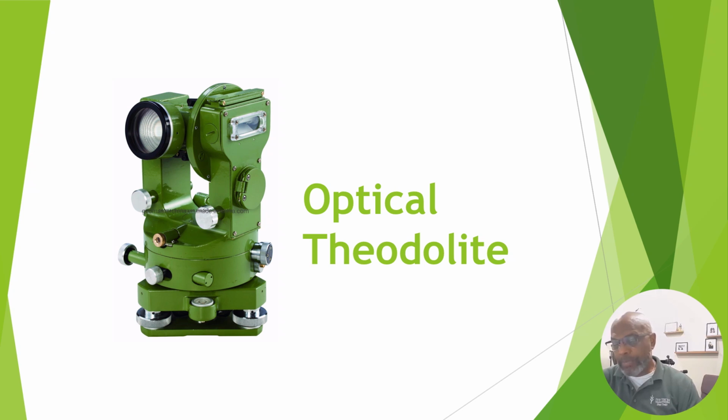A typical optical theodolite may have as many as 20 prisms or lenses as part of the optical angle reading system. With a sharp bump, these can get out of alignment and may render the instrument unusable. So again, we must take care of these things, not dropping them around, not kicking them around, keeping them in the case.